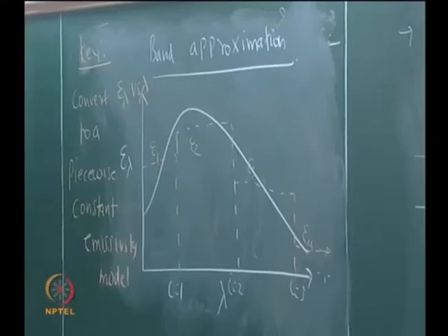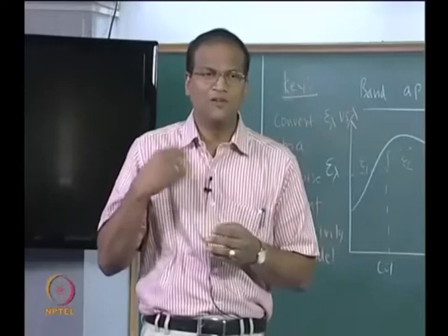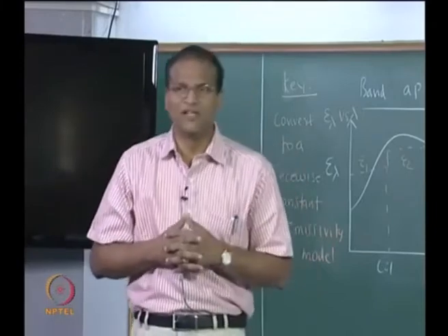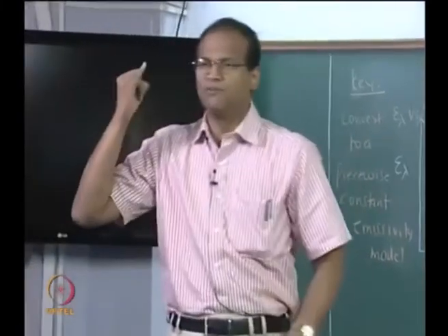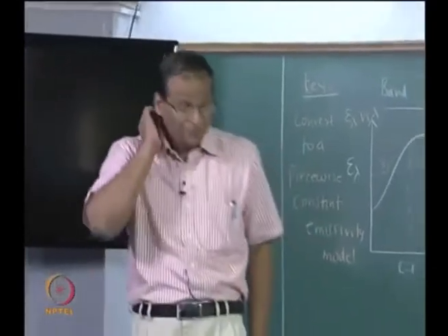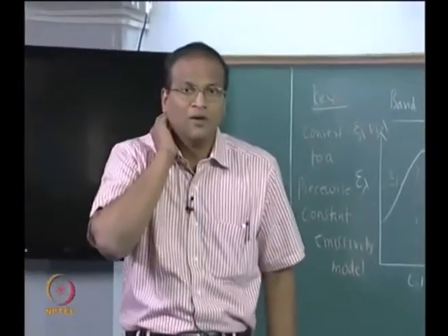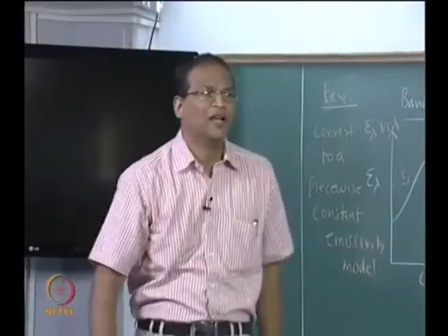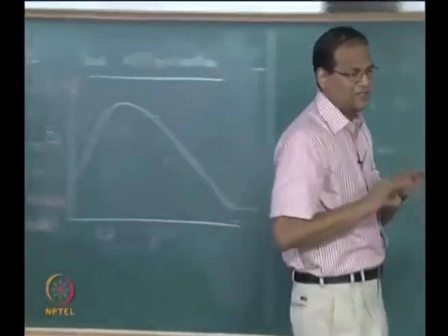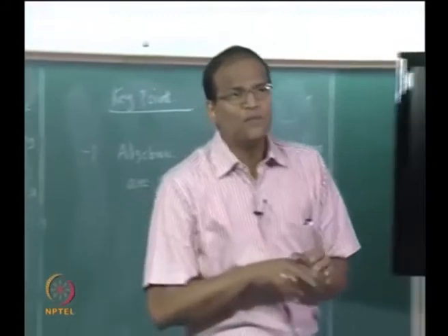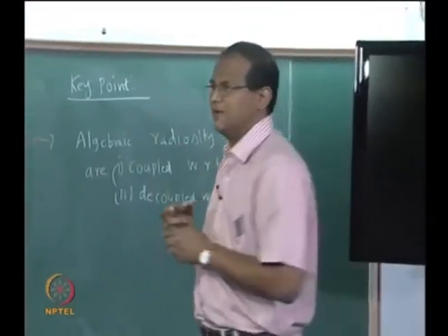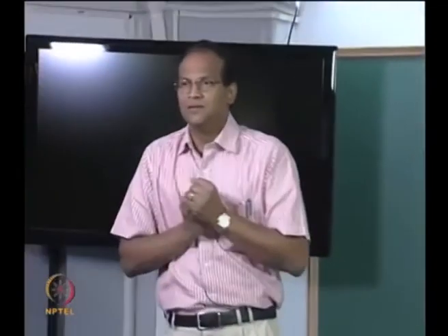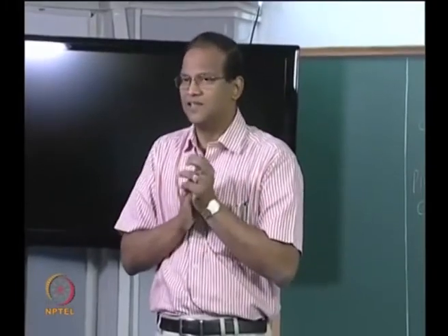The complexity will increase if we employ more bands. Accuracy will also increase as we employ more bands, but it is a trade off between your computational cost and accuracy, right. So accuracy will increase with number of bands, complexity will also increase with number of bands. Accuracy is also critically dependent on how good this piecewise model approximates the non-grey body behavior. That is the final point which I have said is very important. Finally the accuracy of the calculation depends on how good this piecewise constant emissivity model mimics the actual non-grey behavior of the surfaces under question.